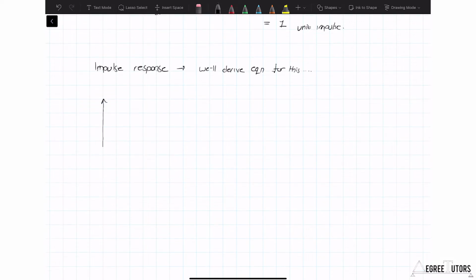So this is just going to be some displacement time history. We'll imagine we're dealing with a damped system here, so we're going to have a decaying sinusoidal oscillation. Some impulse is applied. Let's imagine it's applied at t equal to 0, and we get something like this, right? So we get a decaying oscillation. We'll say that this was the damped response of a single degree of freedom system to the impulse p of t dt.